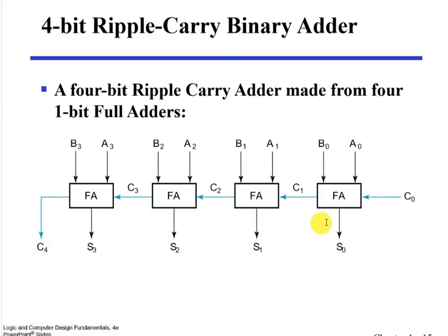So here, as we can see, this is an example of a parallel binary adder that produces the arithmetic sum of two binary numbers, using the combinational logic in each full adder inside. In other words, the parallel adder in this specific case uses 4 full adders in parallel with all input bits applied simultaneously to produce the sum output.